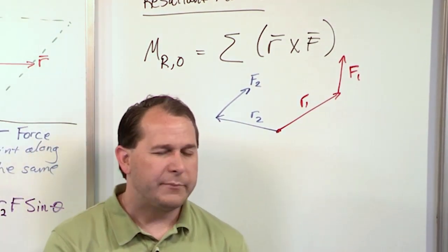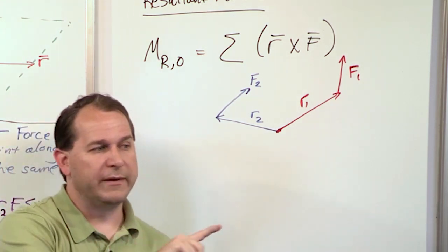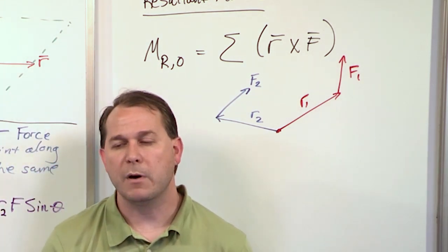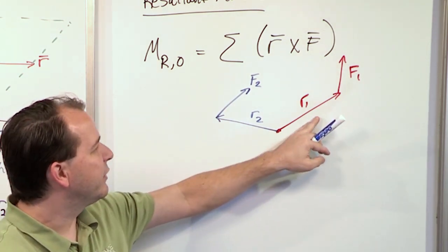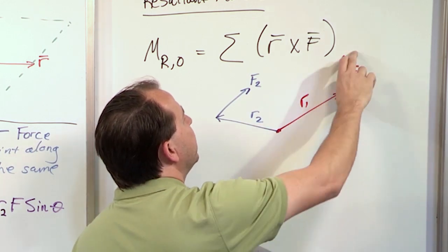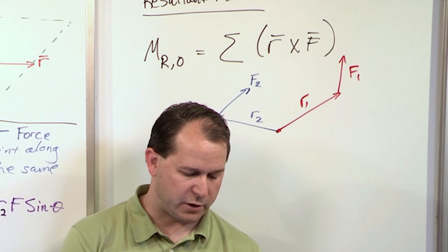And then you can basically do the problems as we've done before. But in 3D problems, I may have what I have here, forces and moment arms going different directions. It's going to be hard to do a scalar calculation here, so just do the cross product. This cross with this cross with this, get the two quantities, boom, add them together, get a resultant moment.